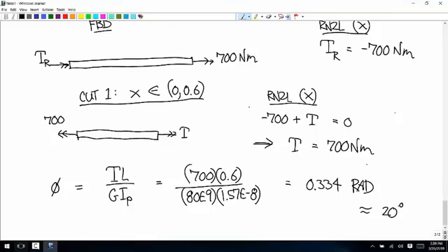So if you had something that was 5 miles long and you torque the end of it, you'd get this thing to rotate a full time around or whatever. That's a huge deformation, it seems like, macroscopically. But each individual, local deformation is still really small because all of that deformation is happening over 5 miles.